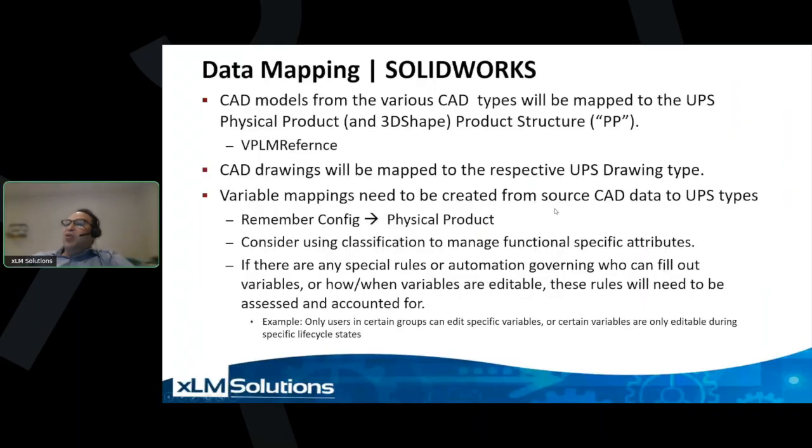You also want to consider if there are any special rules or automation governing who can fill out variables. Again, in PDM, you have logic to hide and control who can see what based on data card rules and permissions. These rules don't necessarily exist in 3D Experience. So if you have any special rules of how data is filled out or who can fill it out, it needs to be discussed in more detail.